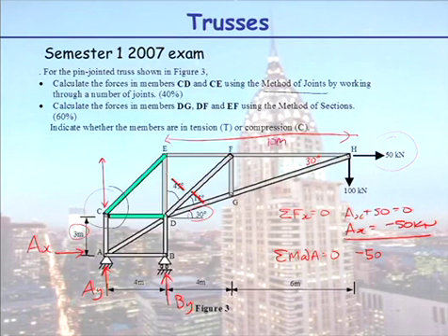So thus, this height here is equal to 10 divided by, hang on, I won't take a shortcut here because then I'll muddle myself up. Okay, we know the length ED divided by 10 is equal to tan 30 degrees. So a bit of trig in there. So that height in here is therefore equal to 10 tan 30 degrees, which when you work it out is 5.77 metres.